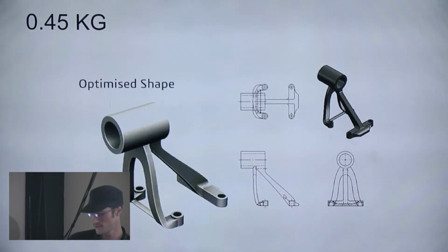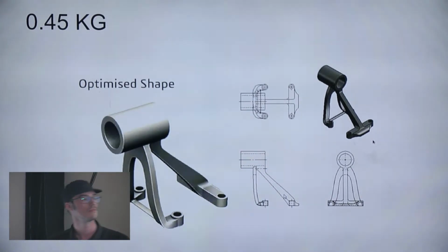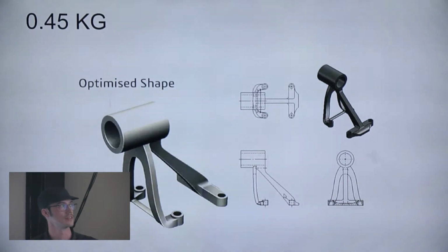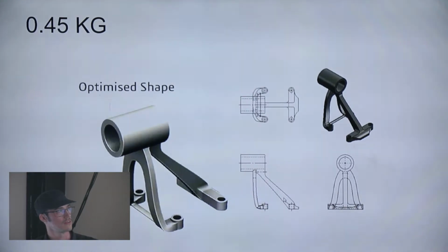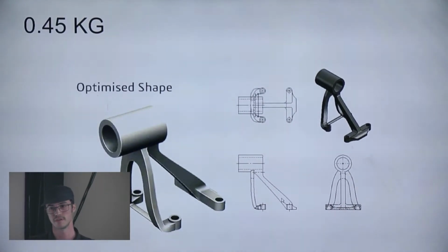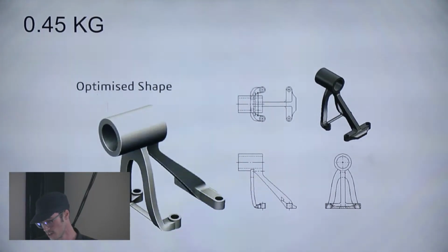And interestingly enough, if you see my mouse, cool. See this foot here? If you delete this foot, this part has to connect to here because it will roll backwards. There's two ways really to optimize. You can optimize for weight reduction or stiffness. So this is weight reduction. This foot stops that center beam from rolling and stops you from having to have 2 beams, one going to each of the bolt points. It ends up being a way stronger way to make it.